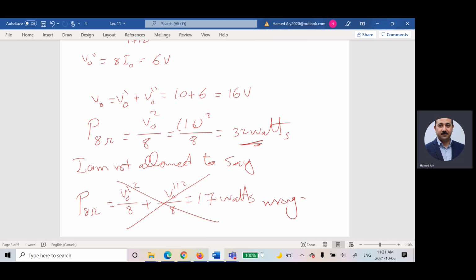So, as a conclusion for what I said, so far we have learned many methods. KCL and KVL, one of them. Find R total and then find I total, and then start to distribute the current using current divider, or use the voltage divider if you know the voltage across two branches connected in series. And then we started talking about the node voltage method, the mesh current method, superposition and the substitution theorem. So we covered many different ways for solving the problem. Which one should I use while I'm solving the problem?